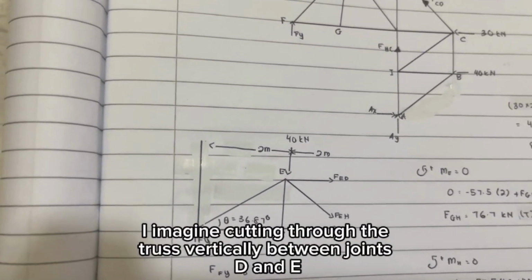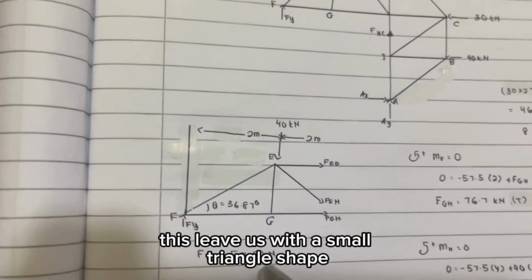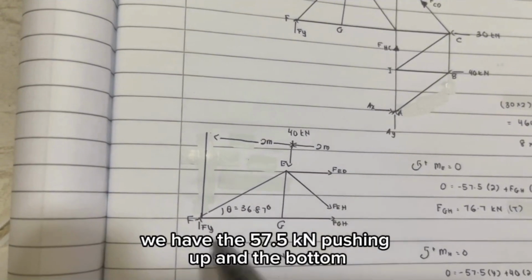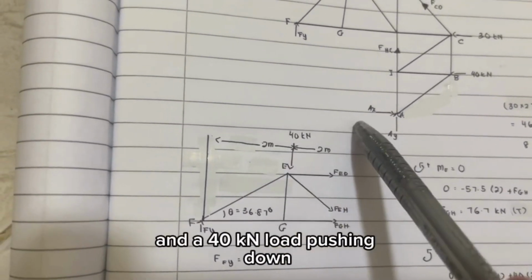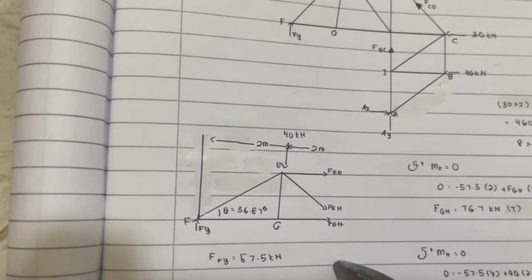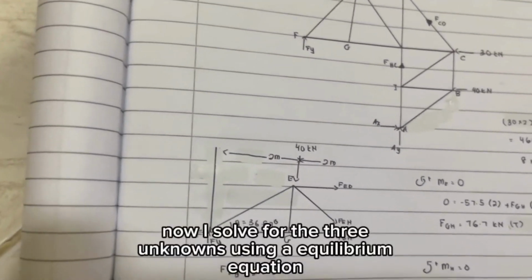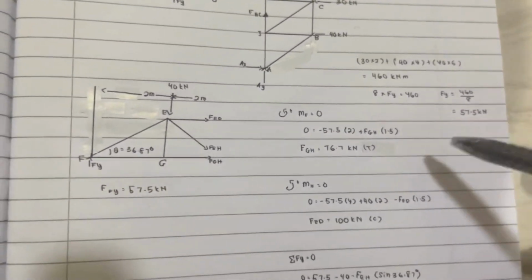I imagine cutting through the truss vertically between joints D and E. This leaves us with a small triangle shape. We have the 57.5 kilonewton pushing up at the bottom and a 40 kilonewton load pushing down. The 3 cut members ED, EH and GH act like internal forces holding this piece in place. Now, I solve for the 3 unknowns using equilibrium equations.